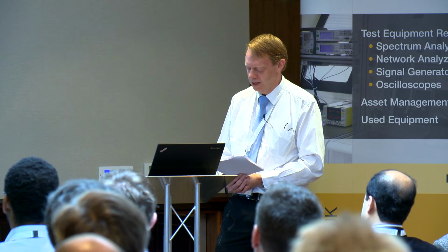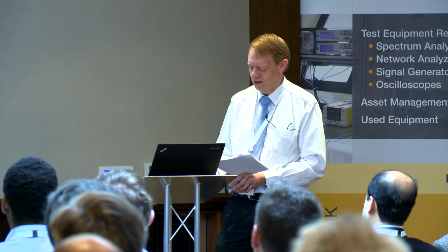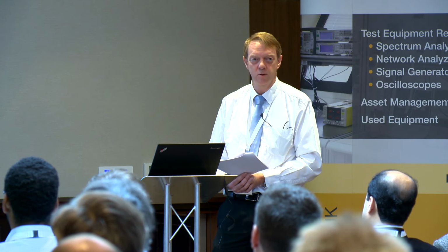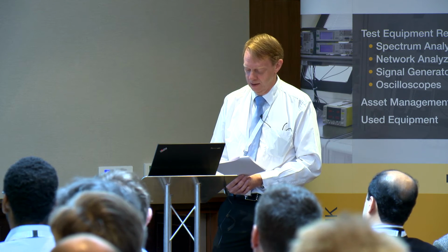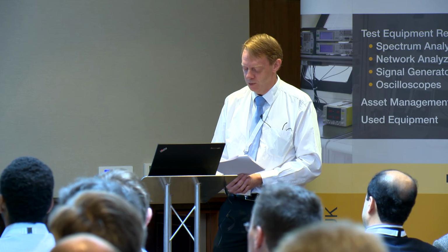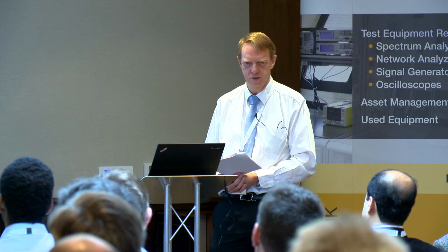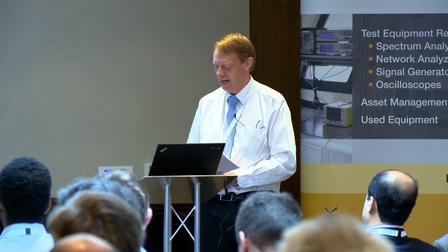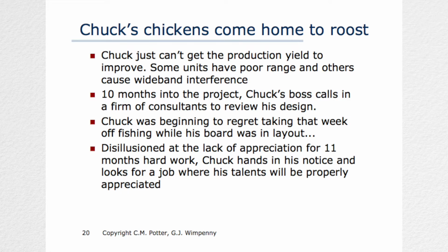They discovered that one of the key components used in Chuck's design can't be made to sufficient accuracy to guarantee all his units work, so a new architecture is needed. They found the reason for the wideband interference was that the VCO was far too close to the digital clock. The only solution is to start the board layout from scratch again. Chuck was beginning to regret taking that week off fishing while his board was being laid out. I suspect that he can have a little bit more fishing time in the near future at this rate.